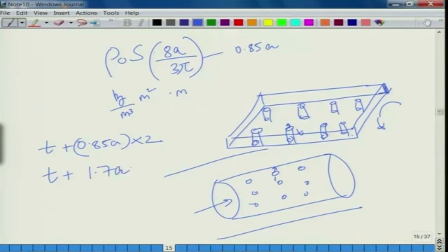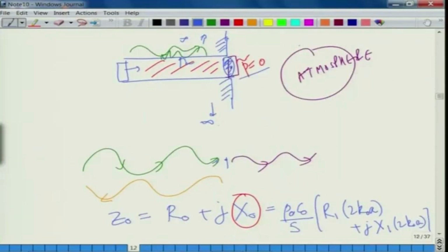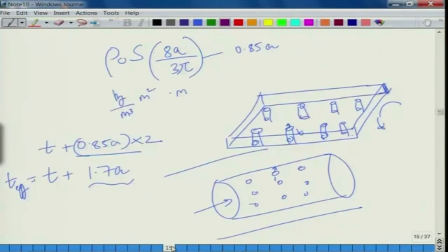It is important in a Helmholtz resonator context, we will soon see why. This is the net effective length, you can call this T effective, and for small tubes it may so happen that the correction term actually dominates the physical thickness of the tube or a sheet of metal. So, the end correction term is important, and that is because the fluid is seeing a virtual or hypothetical extension in here. This thing adds on both sides. I hope I am clear, but we can probably have a question answer session in which you can ask these questions in a more upfront manner.